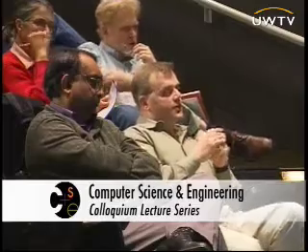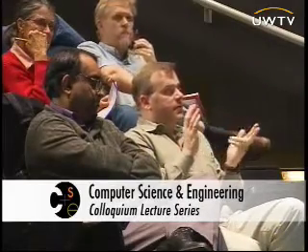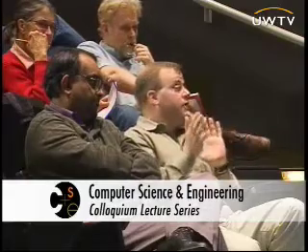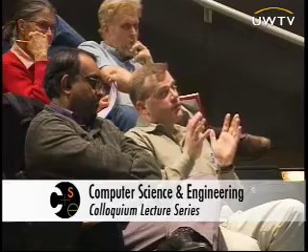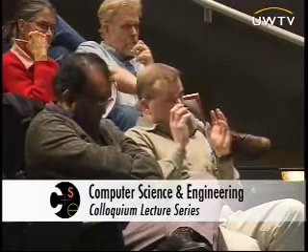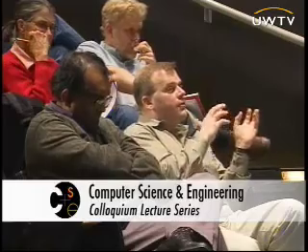If you have two, then like you said, 3 or 4, you start getting a picture. So the peak to average ratio is going to really increase, and things like phase noise in the synthesizer, dynamic range, the ADC, linearity of the transmitter and receiver really start becoming part of the picture, and the power that they would require in order for you to preserve that signal under those conditions. I kind of wonder what if I just used a regular network and did a brute force method for the same amount of power, or requirement. So everything I mentioned requires more power, right?